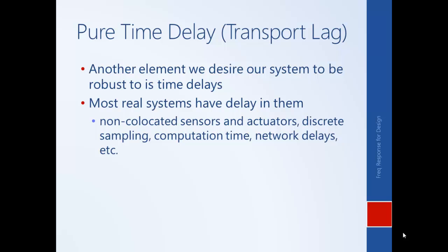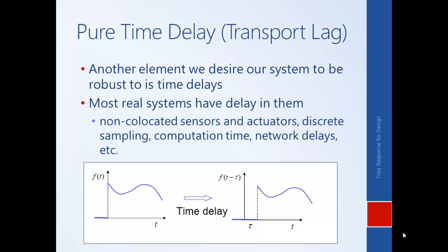Another example that's especially common within automotive applications is network delays. So if you have a wheel speed sensor and you need to send that information on the CAN to the powertrain ECU, then by the time it gets across the CAN, it will again be delayed. And so here's the picture. This is the true function of whatever it is that you're reading, the wheel speed or whatever, and it's been delayed, so by the time your controller actually gets to use it, it's old.